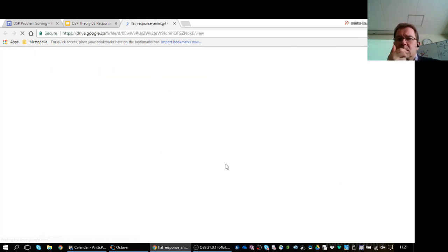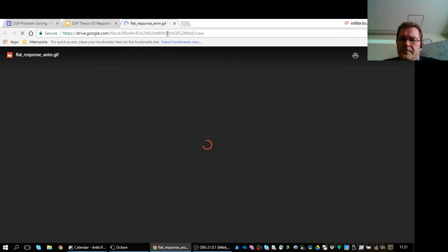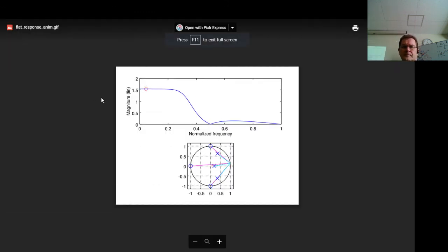Okay, that was nice. What was the other one? Flat response. Oh, okay, flat response. So that's one way of doing a flat response filter. Basically, you have these zeros here to have the maximum attenuation on those angular frequencies, and then you actually adjust the gain here.